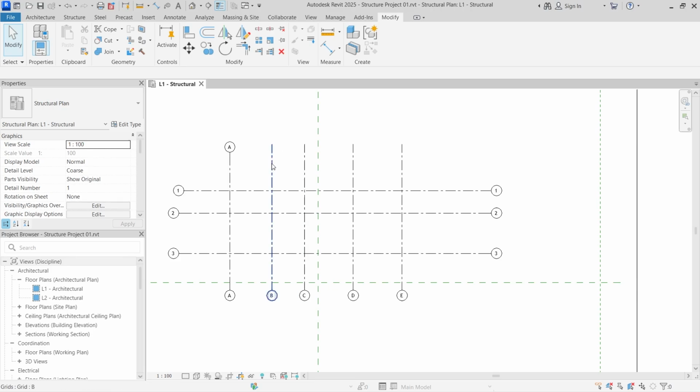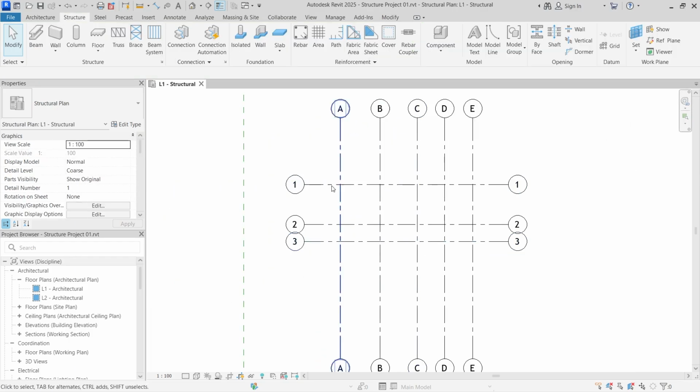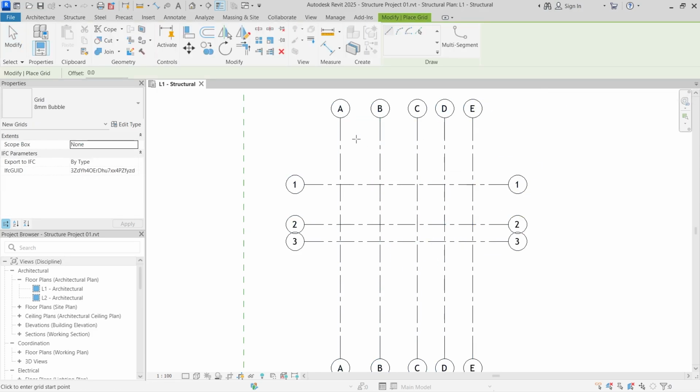So now that we have our grids created, we can go ahead and turn on the labels and also give them dimensions to actually match the structure that we're trying to create. So we're almost done creating the grid lines, and we've put all the spacing for what we're looking for. And then what I want to do is to create one more grid at the bottom right here, but I noticed that this grid actually has to be horizontal and not vertical, that has alphabetical labels.